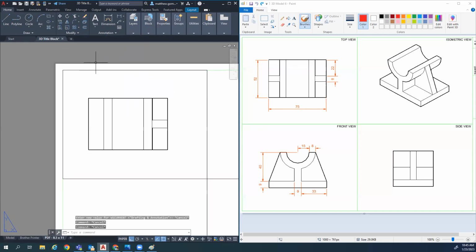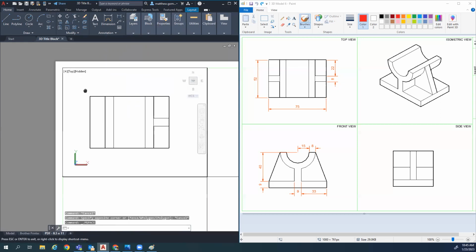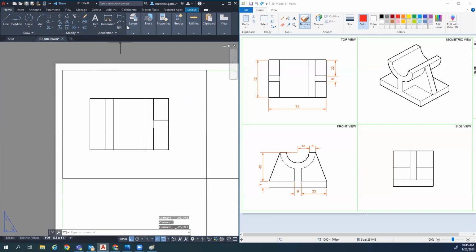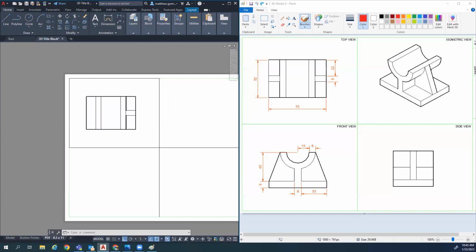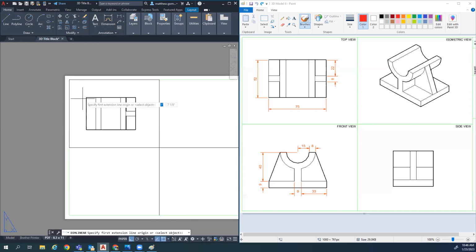But anyway, once you set your view in the correct location, then you just do dimensions basically on the same, not inside, but outside of the viewport. That's the important part. Click there to there. And then it makes your dimensions.